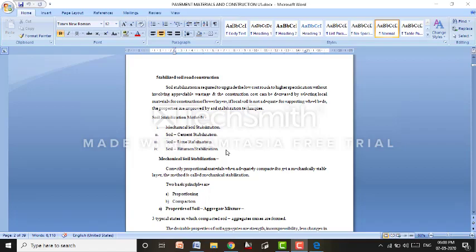Once the formation levels are fixed or formation line is drawn, the next step is to analyze the sections where there is a need of earthwork. Obviously, in all the sections there will be need of earthwork, but in some sections it will be involved with cutting, and in some it will be involved with filling. So, in any of the cases, we need to work on earth. So yeah, maybe we will be involved in cutting or we will be involved in filling.